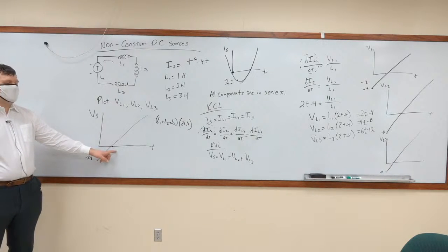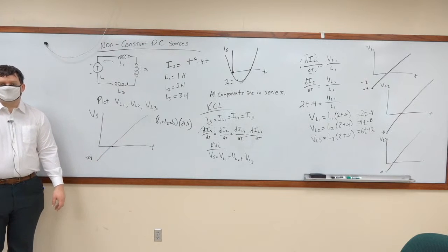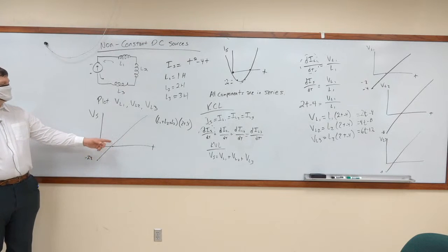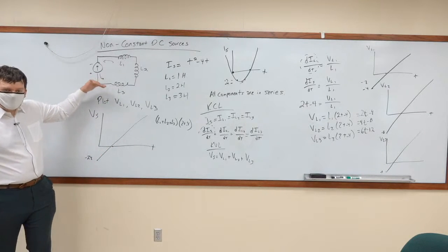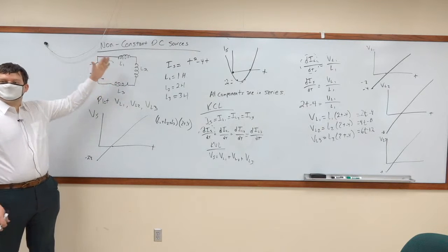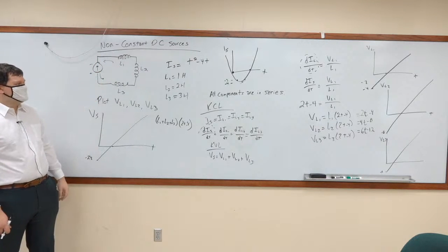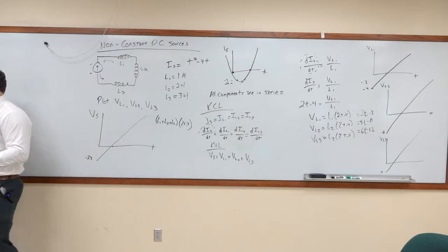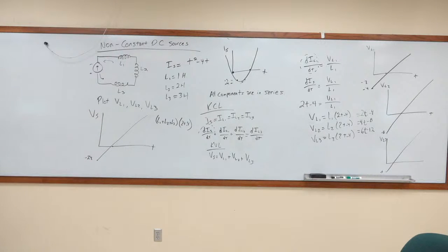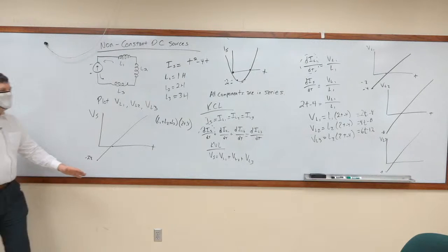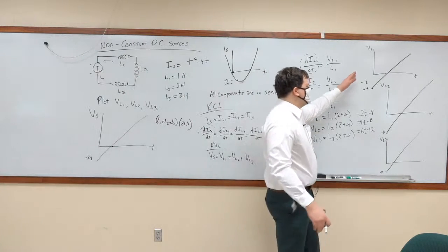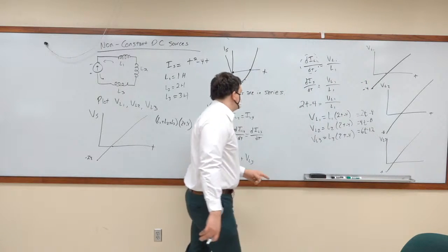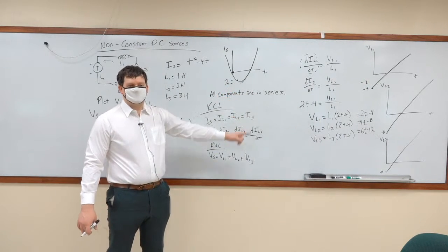To a point where at t equals 2 seconds, it stops reducing their energy. Now, the current is still flowing this way through the system, but at t equals 2 seconds, this now starts putting energy into the components. It's no longer pulling energy out, it is now pushing energy into the components, which is why they have a positive voltage. But you still have a negative current.